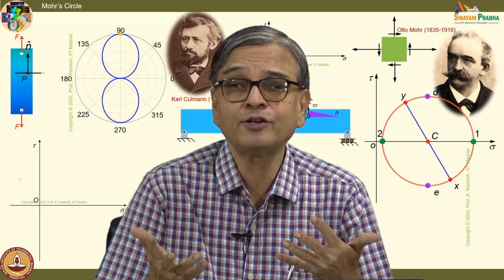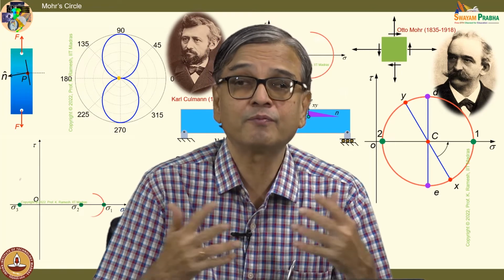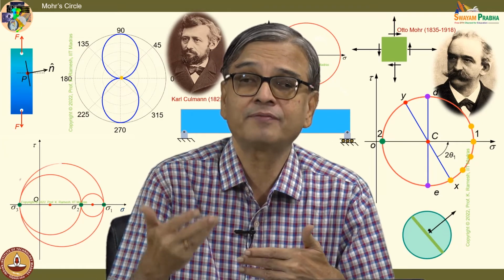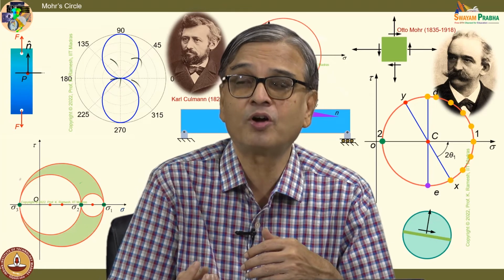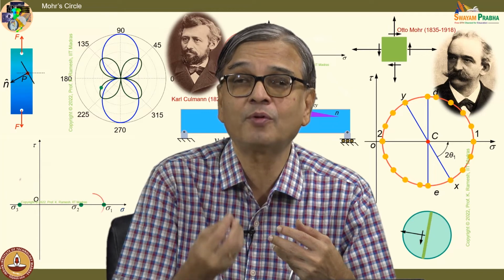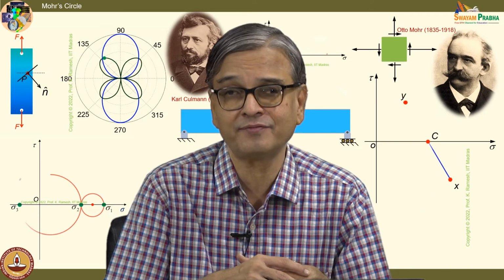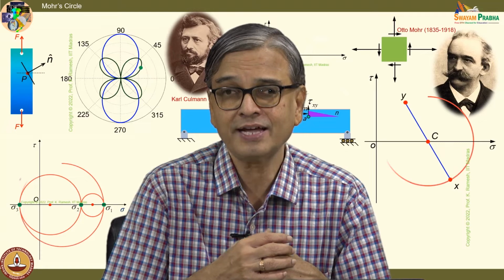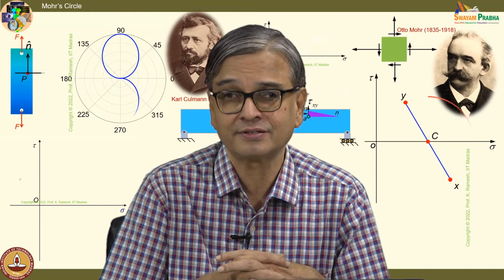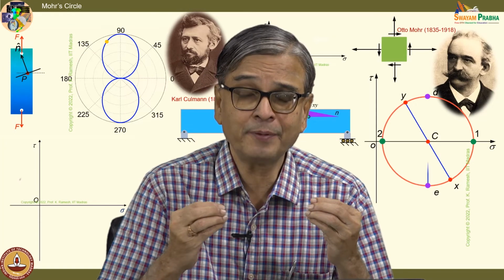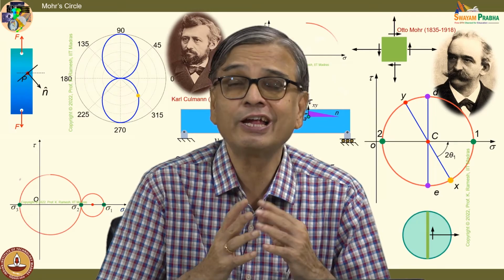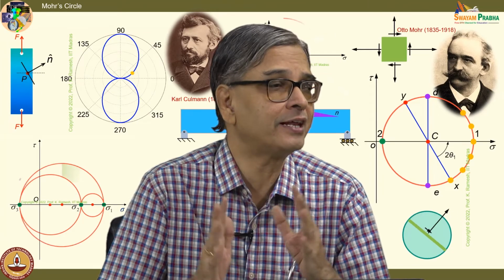It varies from material to material, and with modern manufacturing you also have to find out, for example, when you have rapid prototyping where the models are grown. When you grow the model you may have some gaps in between, micro gaps. How do you handle it? What is the way the material behaves? So, depending on the manufacturing method, and also as newer materials are being developed, failure theories keep appearing in the literature.